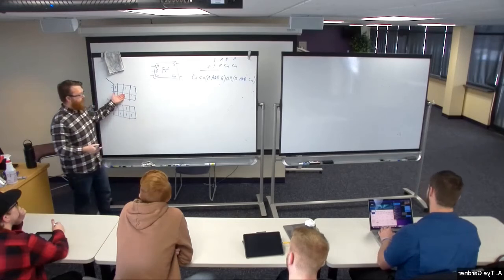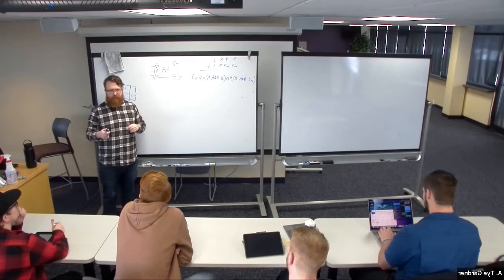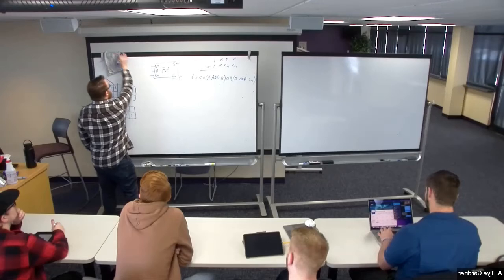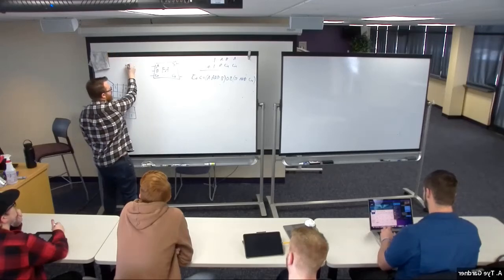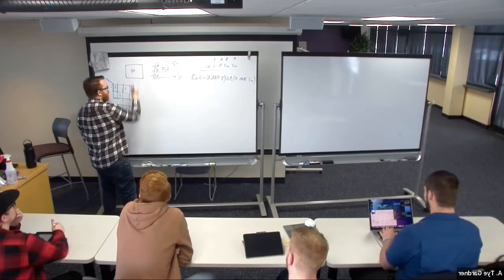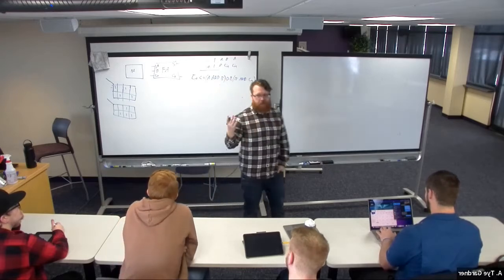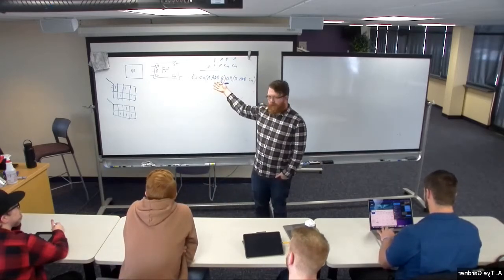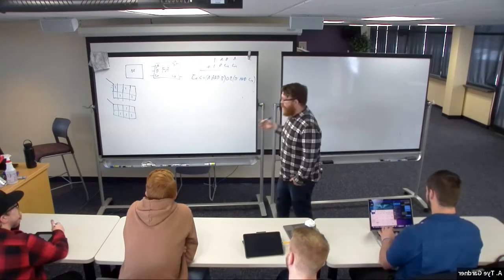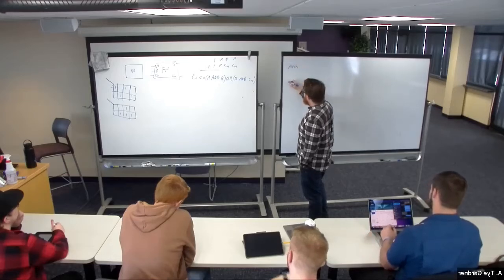I do the same thing for the sum circuit, right? There's 2 different circuits inside of this full adder, just like you built 2 different circuits inside of the previous lab. Then it's just a matter of taking these. And if I want to turn this into the 2-bit adder, this is hopefully a review for everyone. I take another instance, right? So the entity is declaring how it interacts with the world. Then you make a component declaration, where the component declaration goes in between the architecture